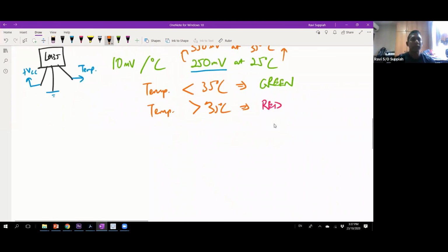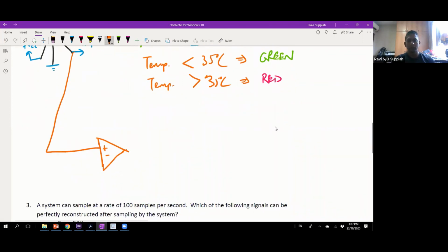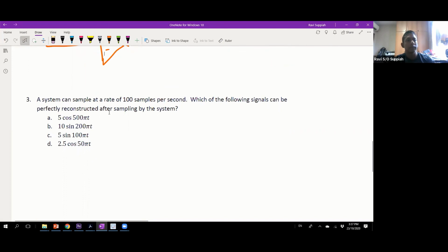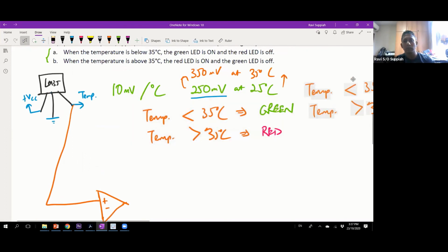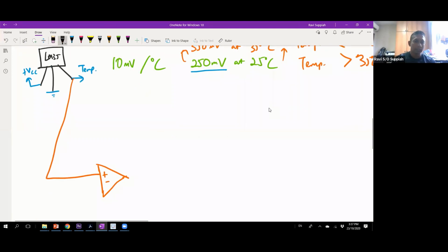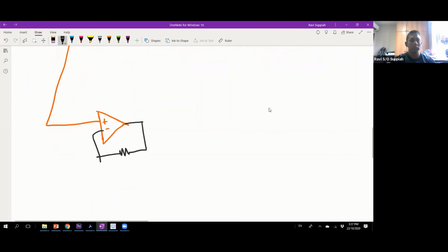So the first thing is, I'm going to take this signal and amplify it. To amplify it, I can pass it through an op-amp, and you can use any resistor pair combination. It all depends on what gain you want. So I'm going to connect it up this way, and I'm going to use 9K and 1K. Why? Because 1 plus 9 over 1 will give me 10. So what I'm going to get here is 350 millivolt multiplied by 10, so what I get here is 3.5 volt.